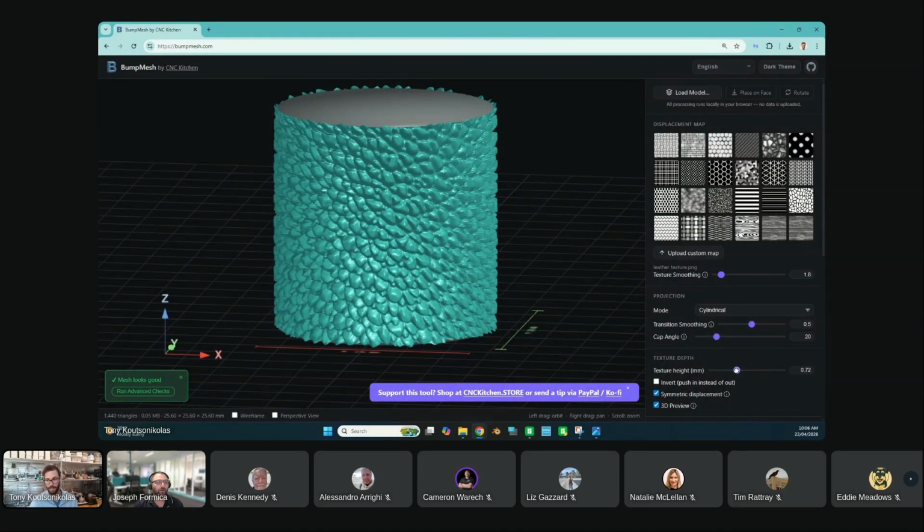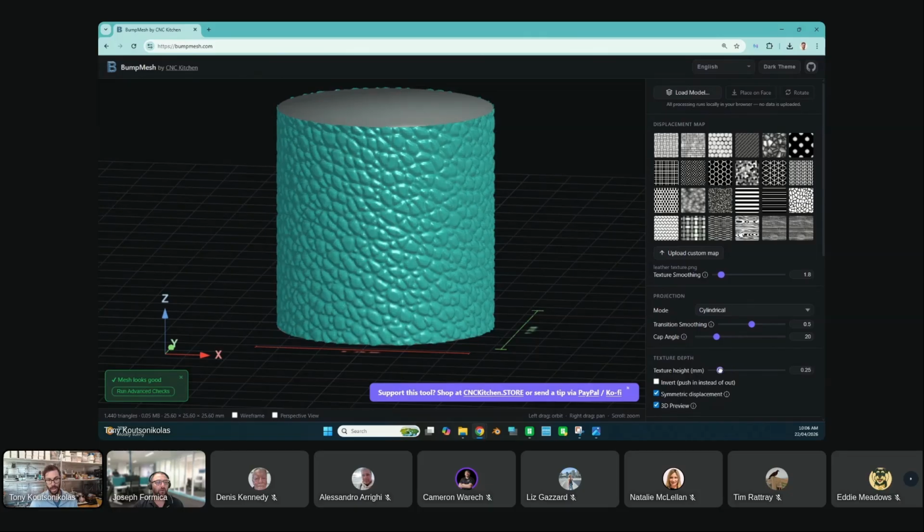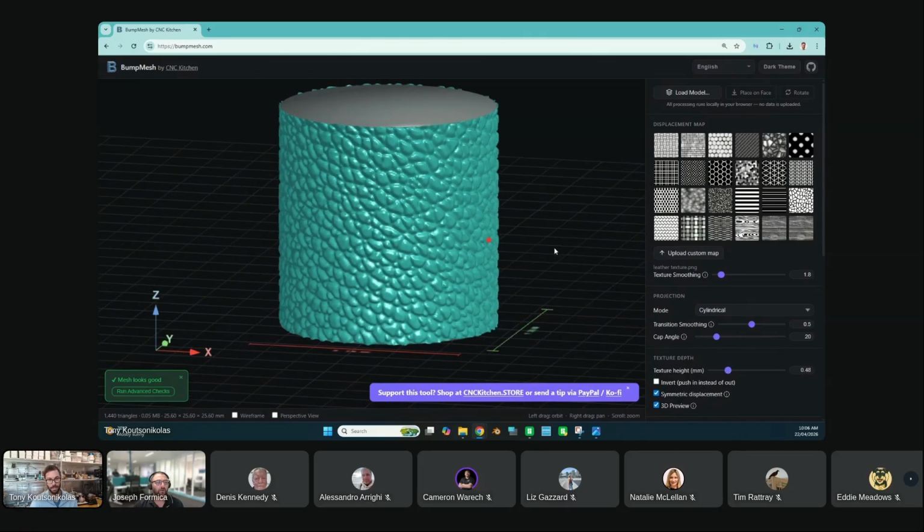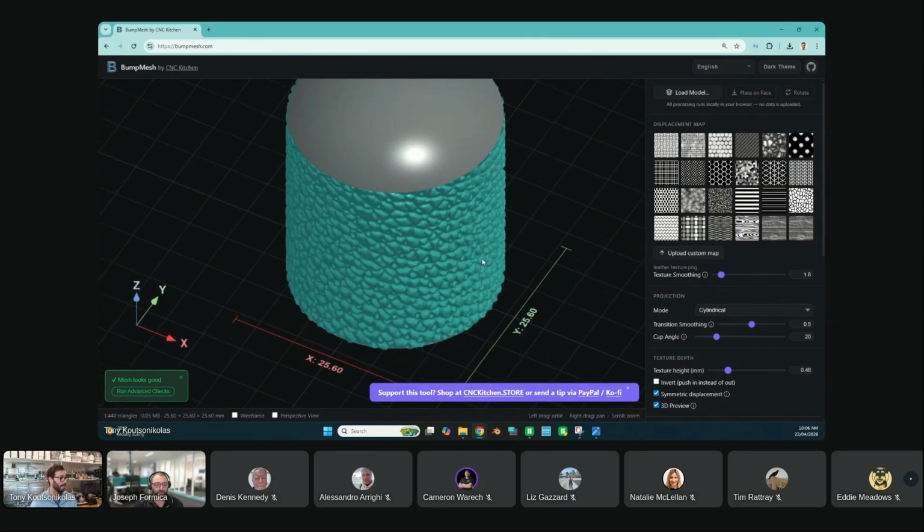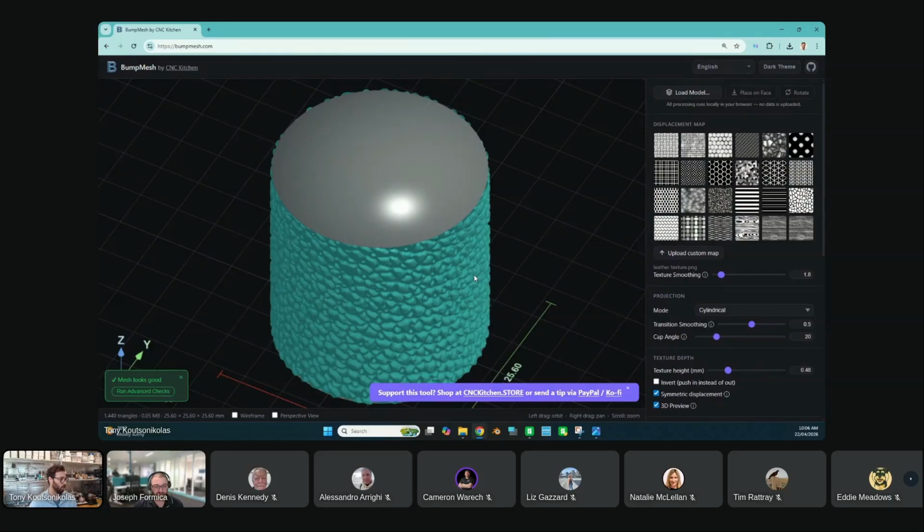So even if I did this texture, at 0.25 or 0.5, you would be really surprised how much extra rigidity you get from that texture. So you can change mechanical properties like that. Now, I've just shown you that with 0 infill so that in your head it makes more sense. This also works when your parts are solid, right? Because you're adding more geometric stiffness to it.